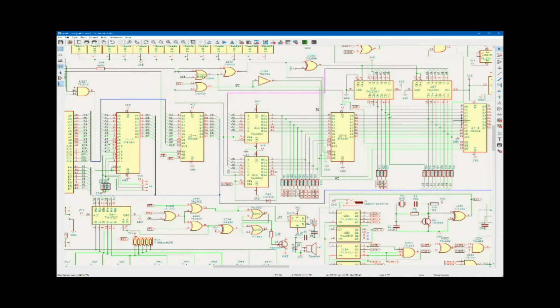The Jupiter Ace was originally designed with a pair of 2114 4-bit RAM chips. The guy who designed this project replaced them with a single HM6116, which is an 8-bit RAM chip. He made that substitution and maybe he had a RAM that worked, but the ones that I have do not at all like that the write is started 60 nanoseconds before the address bits are there.